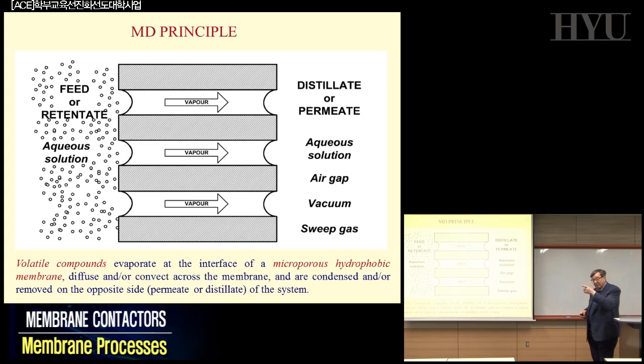That's why some of you in this department and all around the world are working more and more to realize membranes that in reality have a similar configuration, with all the pores, as much as possible, of the same diameter. In such a way you can predict the appropriate conditions and parameters for running membrane distillation the right way.